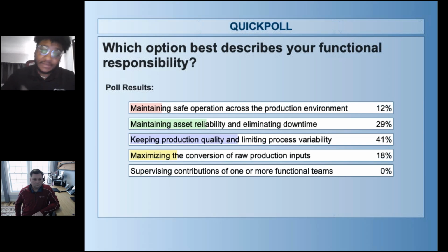But CLPM does absolutely have a wide variety of applications to not just ensuring process variability, but, right, ensuring you're safe, that your loops are operating within safe constraints, that your valves are operating as they should be, and that you are not missing out on any potential throughput.